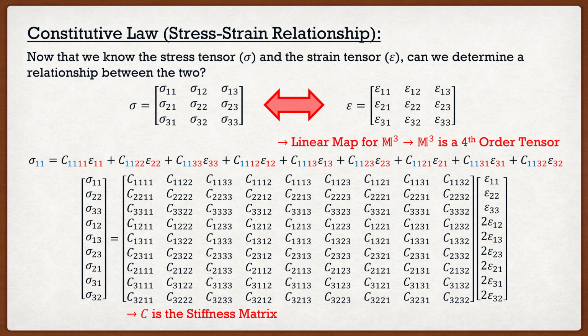Now again, a stiffness matrix C is something that's multiplied by the strain vector to give us stresses. If we multiply a matrix by the stress vector to get strains, as you guys will see a little bit later, it's actually called a different one. So this C matrix, stiffness matrix, this one's multiplied by the strains to give us stresses. And we'll talk again more about that a little bit later.